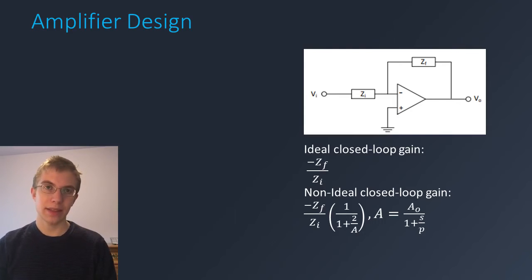As long as A is a large value, the output of the amplifier is largely unaffected, since even though the pole of the op-amp on its own is very low, the feedback of the op-amp that has been added sends this pole to a very high frequency, again as long as A is a very large value. Note that the impedances are complex and can be represented by capacitors and inductors in addition to resistors.